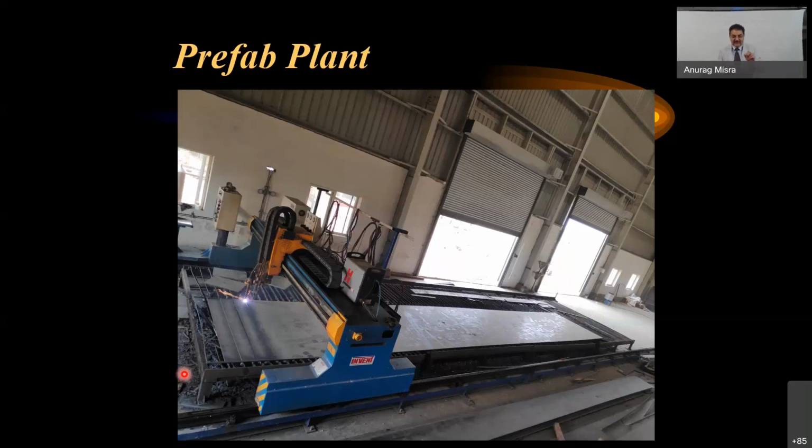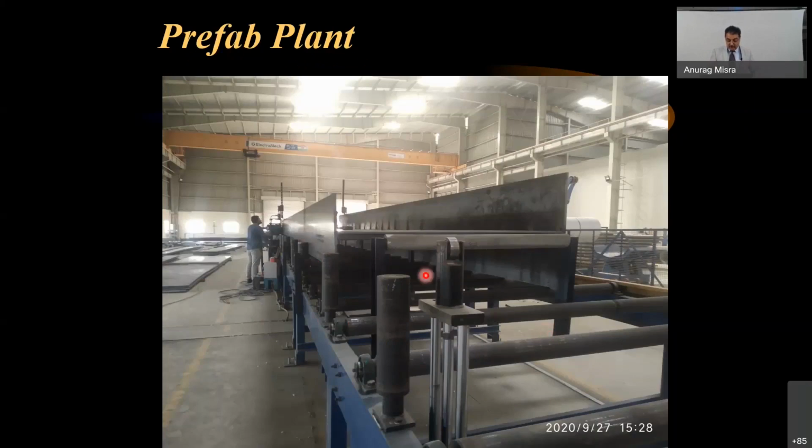So this plasma cutting machine, each cut is taking a very small amount of the material, and a very neat cut that is not possible by any other means. And you don't have to do anything, just start, feed the drawing, and all the components, it starts from here, it will move to this point, and all the components would be cut. And once all the web, flanges, stiffeners are cut, then they are brought to an assembly line where the sizes are to be already arranged